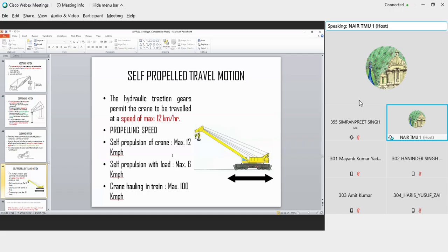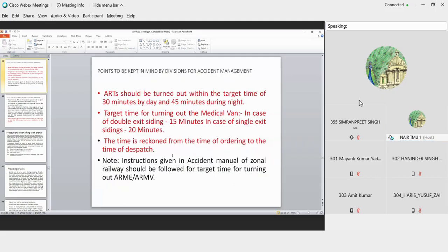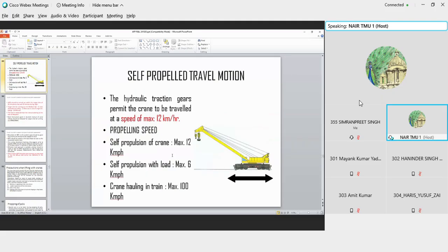Launching a girder means that if you are putting a span of a bridge, you pick up the girders with the help of this 140-ton crane and start placing them to bridge the river. In that scenario, the crane is traveling light. In all other conditions, when the crane reaches the accident site, it is propped. And what propping is, we'll see later on.